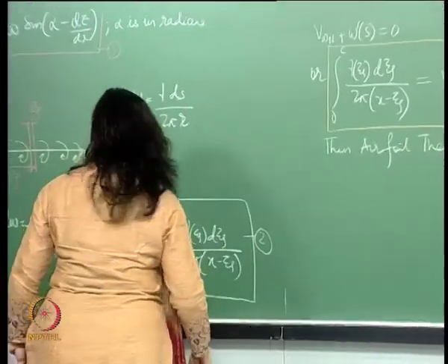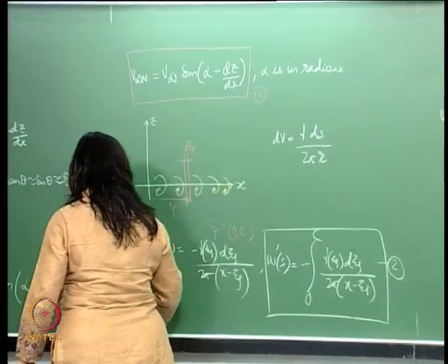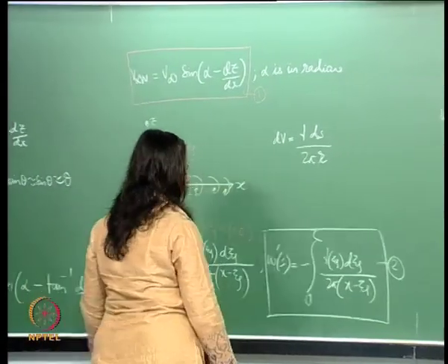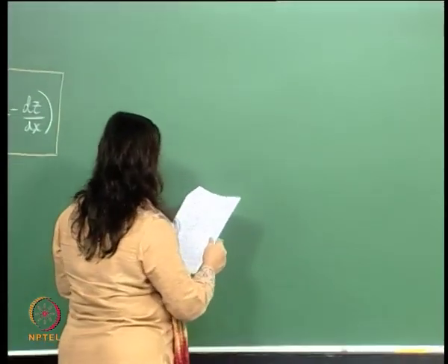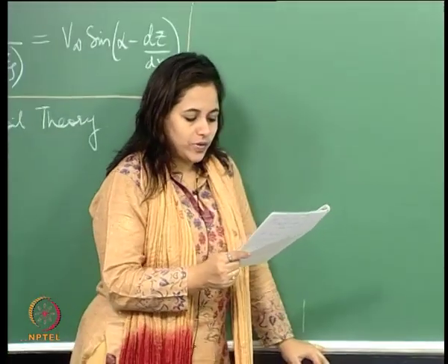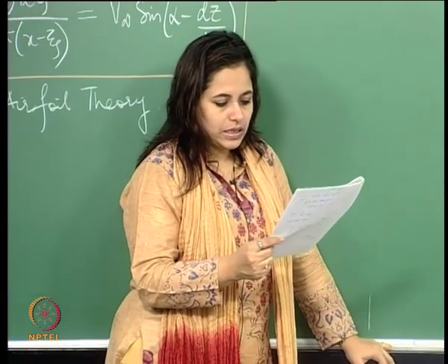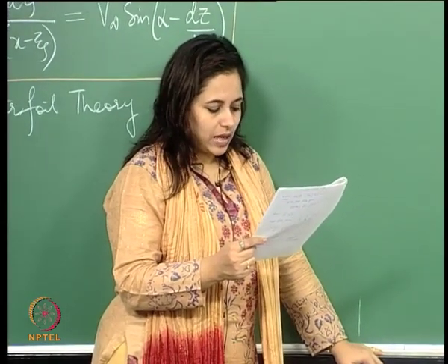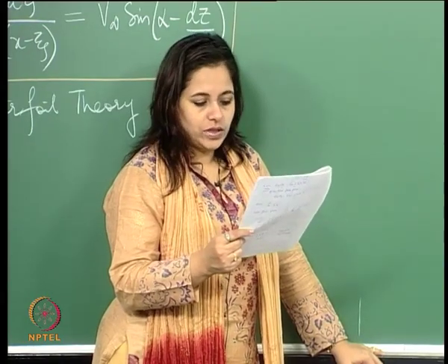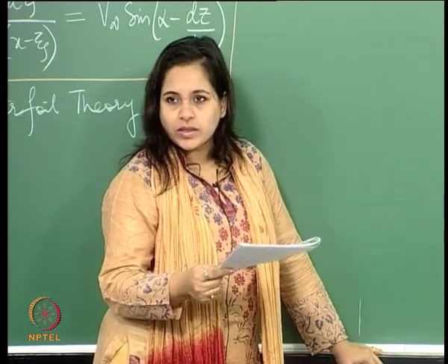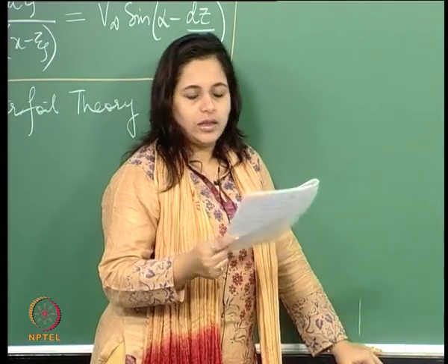So if I may remind you what we were going to do: we had a flat plate of a certain chord length c, at an angle of attack of alpha in a supersonic free stream. So use a linearized theory to calculate the CL and CD.